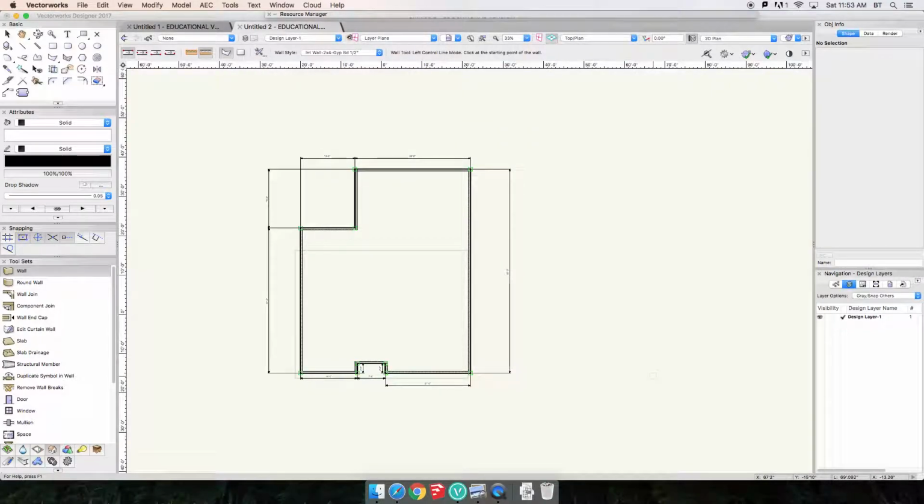For exterior walls, we've measured from outside of sheathing to outside of sheathing. Interior partitions, we measure to center. So if we're referencing off an exterior wall but drawing an interior partition, we're measuring from the exterior sheathing to the center of our partition. Between interior partition to interior partition, it's center line to center line. Does that all make sense?